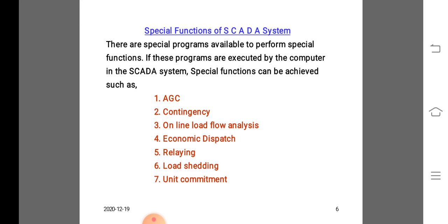After that, the monitoring function has measuring and displaying of current, voltage, frequency, active and reactive power, energy, temperature, etc. Alarm function, storage and evaluation of time-stamped events. Then the protection function. The substation protection function includes the monitoring of events like start, trip indication, and relay operating time, and setting and reading of relay parameters. Then protection of bus bars, line feeders, transformers, and generators.